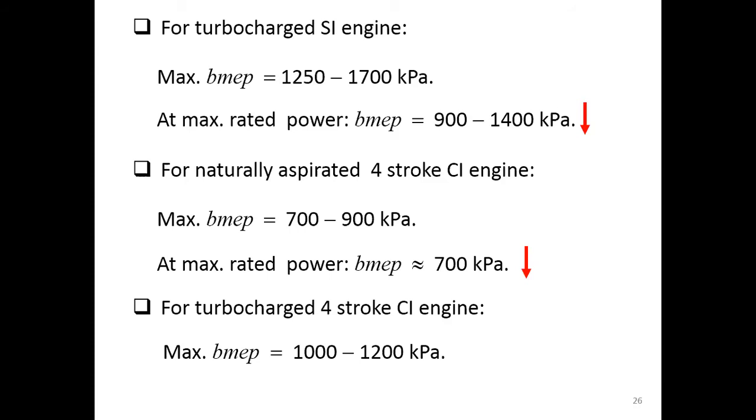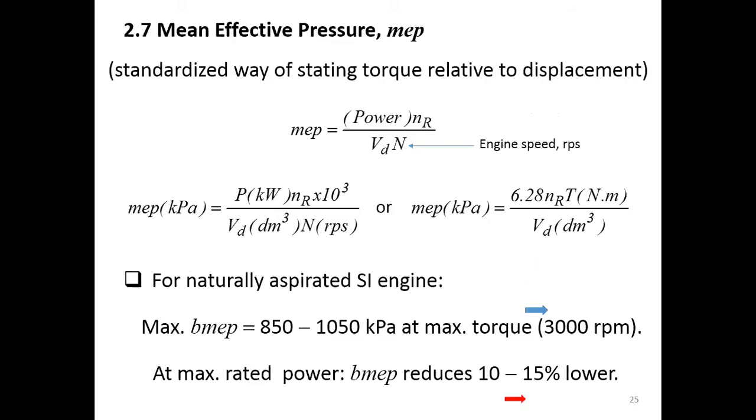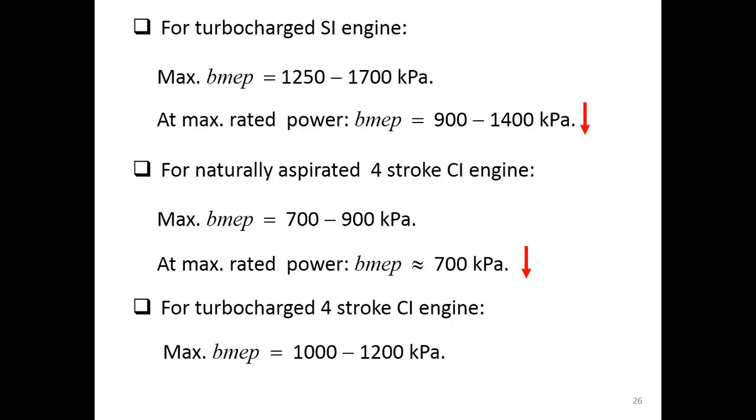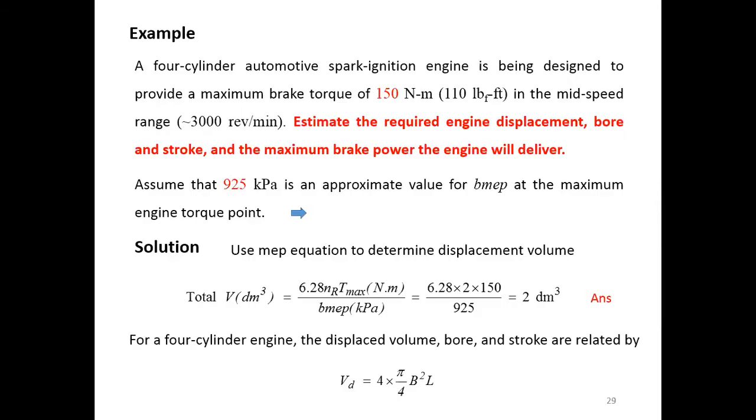The thickness is conventional, the sizing is conventional. The length of the connecting rod comes out in the conventional length, or within the length that they used to produce. So that makes it easy if you go by conventionals. That's the reason why I give you all of these numbers. The mean effective pressure is not just a number that you look through, you can use it for your design. That means I came up with a design example that lets you go back to all the numbers that I mentioned to you.